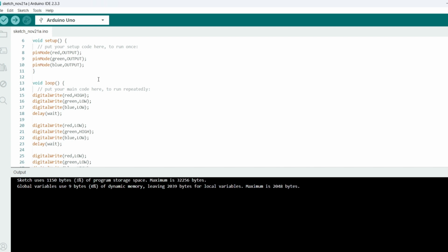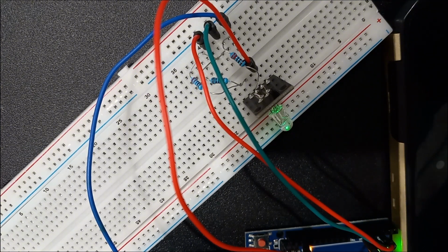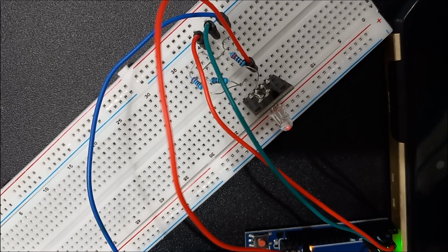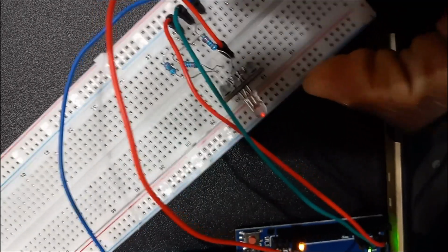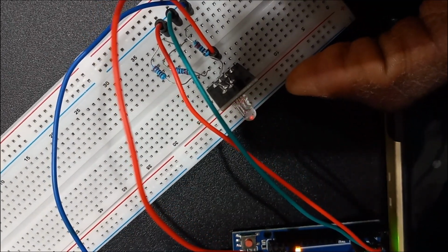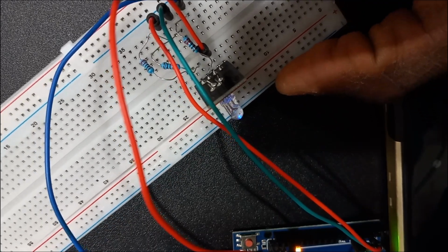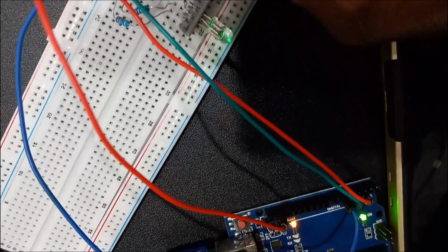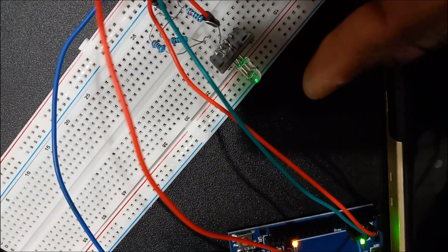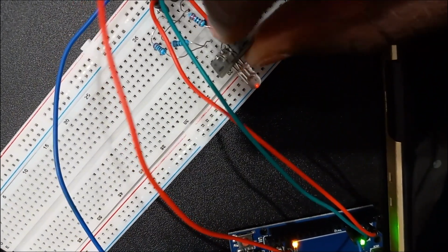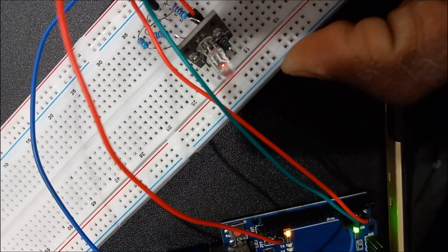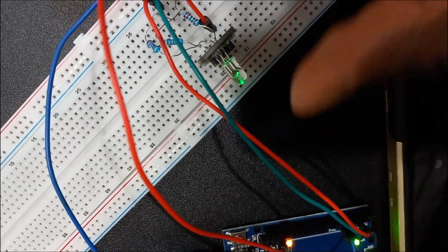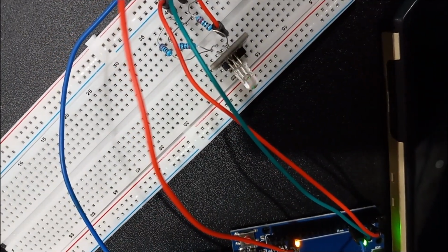Give me a sec. All right, I told you all my LED was cooked. I've uploaded the code and it's not even that bright. I think I used it one time without resistors and, well, this is the result. So always use a resistor. I'd encourage you to always use a resistor. But if you have a Common Cathode RGB LED, it should work. Mine is not really the usual kind you'd have, but it should work. All right, let's just move on.